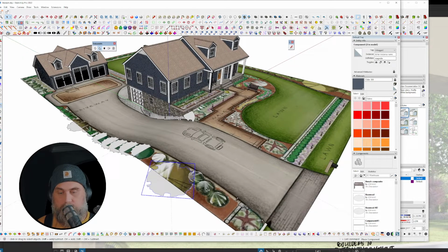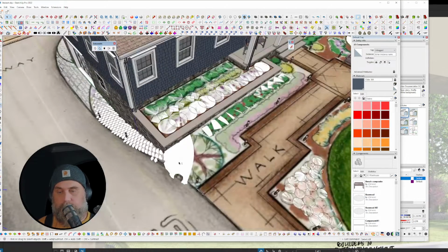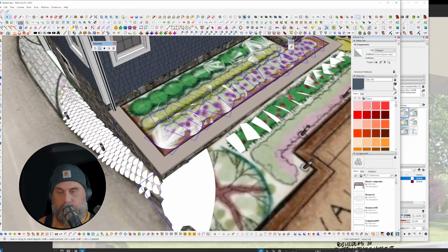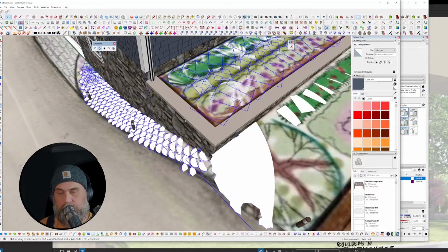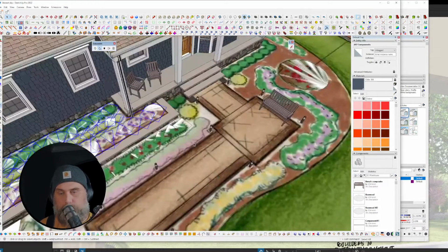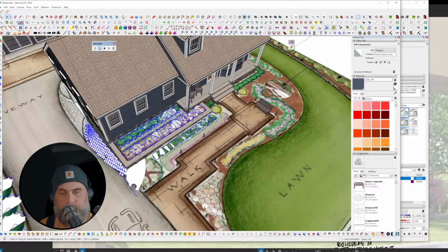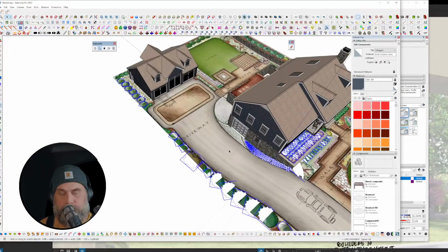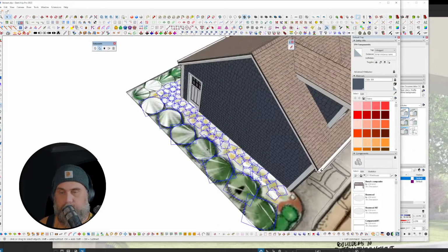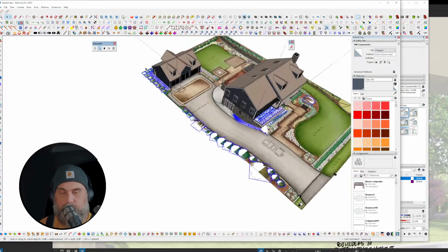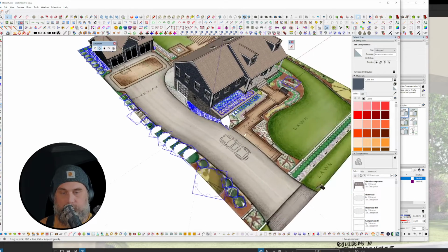So what I do is I'll just get in and grab all of my plant symbols. I'm going to use Selection Toys, select instances, component instances. Basically it lets me select one, run the keyboard shortcut, and then it'll select all of the instances. That's a part of Selection Toys that'll become available in your shortcuts if you download and install that. So we're going to grab that. That's all of them.